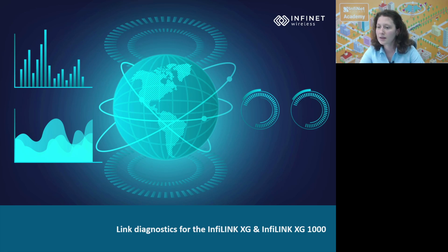For the spectrum analysis, if one of the polarizations is affected, we won't have any values. No, you will have values. As we saw, the spectrum analyzer allows you to scan each polarization separately, or scan them both, and it will show you where the interference is present. You saw that when we have interferences, we have some spikes, and if you go with the cursor over the spike, it shows you the level of interference and the frequency where it is present.